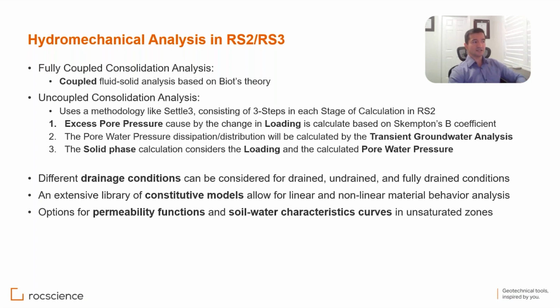Doing all these analyses, there are different drainage conditions that we can consider for the simulation. It could be drained, undrained, or fully drained. I will explain these along the webinar. We have an extensive library of constitutive models that allows for linear and nonlinear material behavior analysis. And we have options for permeability function and soil water characteristic curve that you can apply in the unsaturated zone.